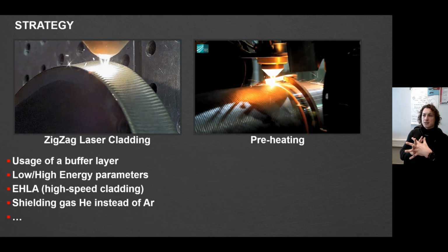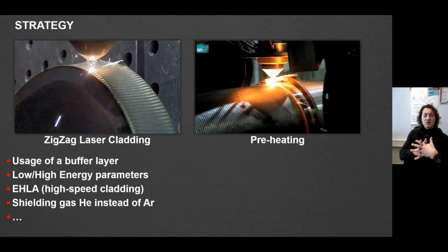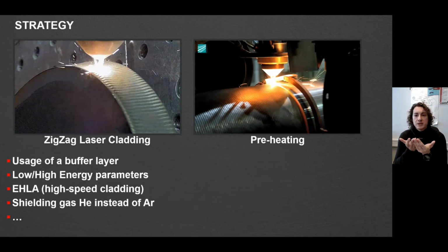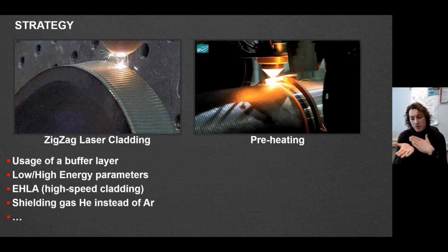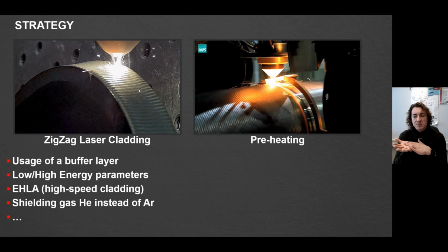Sometimes we have to understand that those approaches are not enough. If you have been working with welding, then you know a very general rule. To have a crack-free coating in terms also of interaction with substrate, you have to be as hot as possible or as cold as possible. So sometimes you have to understand that putting directly a hard coating on certain substrates won't simply work.